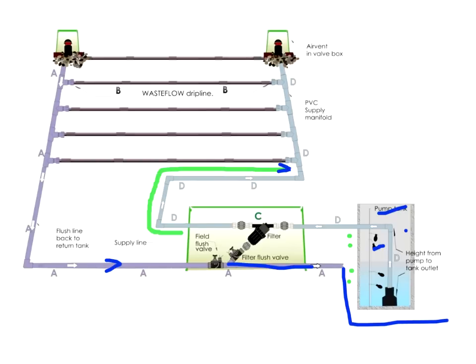And you've got your 2 valves to operate the system, and you pump on and off with the floats. These are air vacuum relief valves, which are critical because when you switch the system off, it's going to drain. The drip line is full of holes. It's going to drain. And when it drains, you're going to set up a vacuum. And when you set up a vacuum, you can suck dirt back into the system. So you must have air vents correctly placed at the high points in the system, and a minimum of 2 per zone.